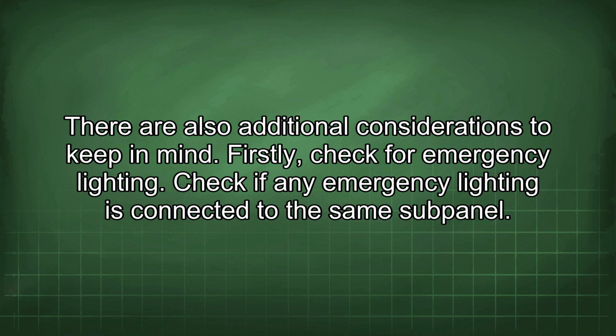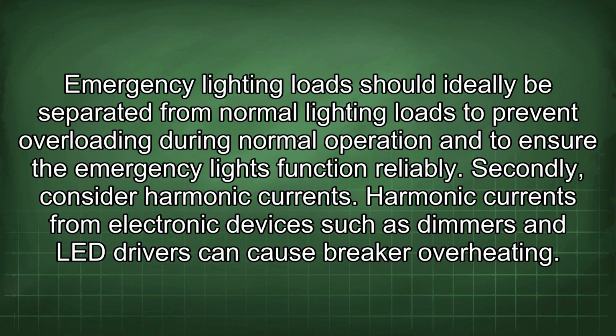There are also additional considerations to keep in mind. Firstly, check for emergency lighting. Check if any emergency lighting is connected to the same subpanel. Emergency lighting loads should ideally be separated from normal lighting loads to prevent overloading during normal operation and to ensure the emergency lights function reliably.